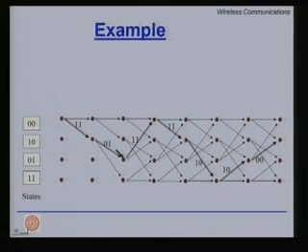So, n naught is 2. By depiction we have shown that 2 bits are thrown out for every bit that comes in. Right? So, we have been able to identify a lot just by looking at the trellis diagram. So, if you are asked to design a convolutional encoder, it suffices to give the trellis diagram and vice versa.